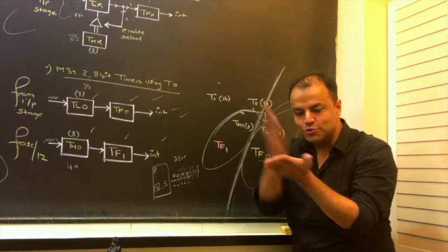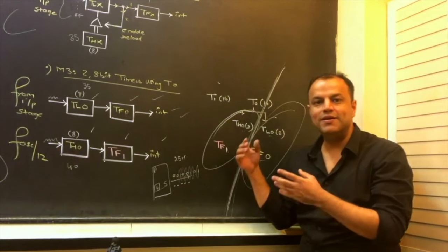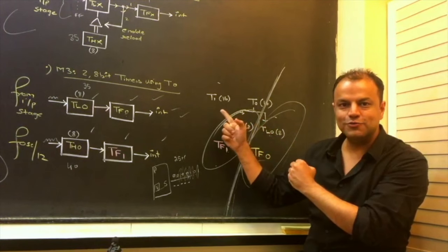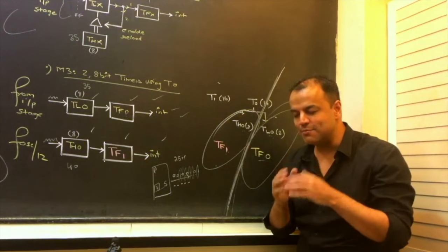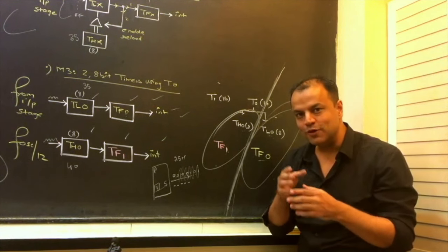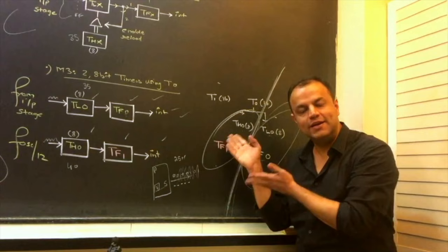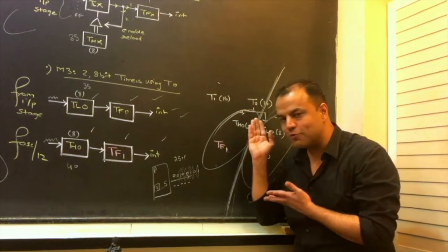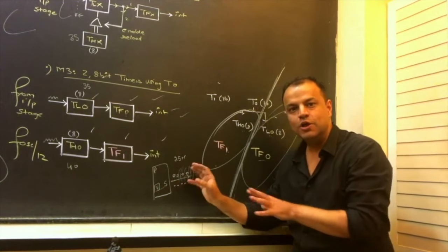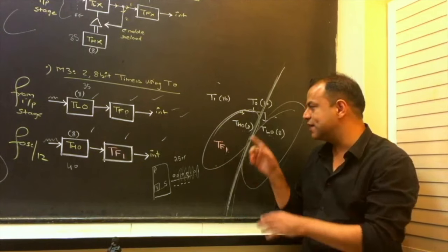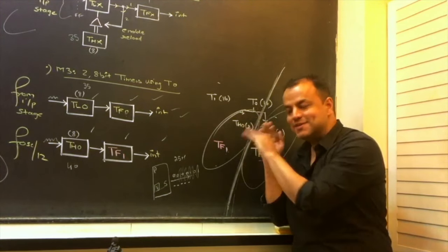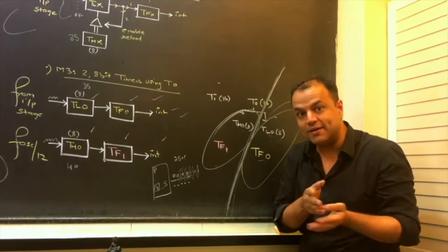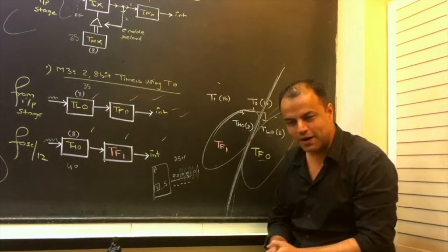What do you do? You split your timer 0 into two independent 8-bit timers. Use up all the resources of timer 1, doesn't matter because timer 1 doesn't have to report to the processor. What did I say? Timer 1 can count, timer 1 can even overflow. It cannot inform the processor. It doesn't have to inform the processor because it's not working with the processor, it's working with the serial port. So it says, take away all my resources, I don't care. So timer 0 lower byte and timer 0 higher byte become two independent 8-bit timers. Yes, they are 8-bit, but at least they are independent timers. That means you understand how powerful this chip can get.